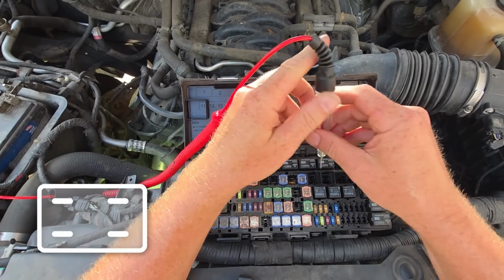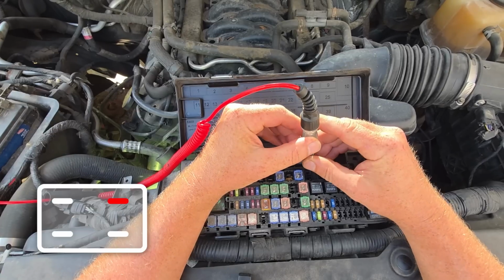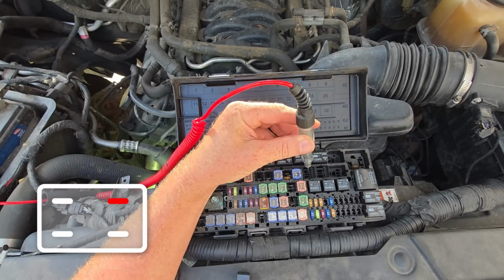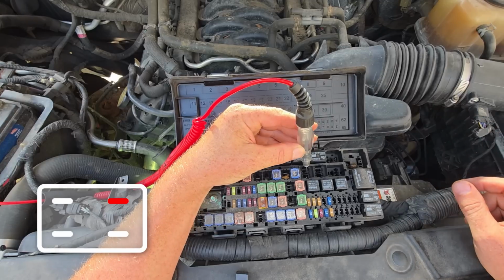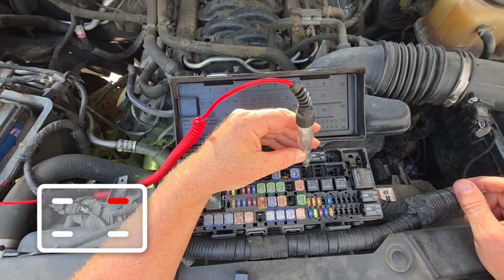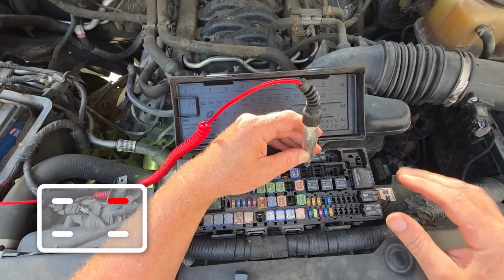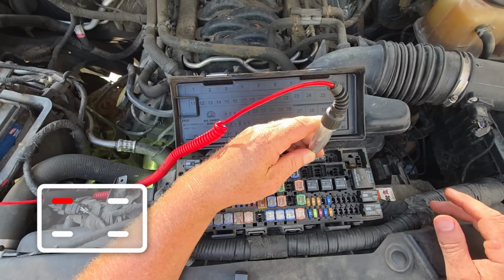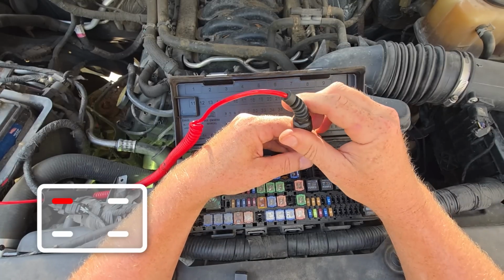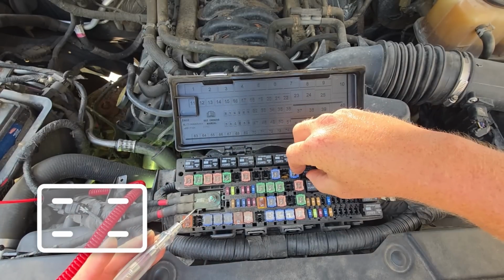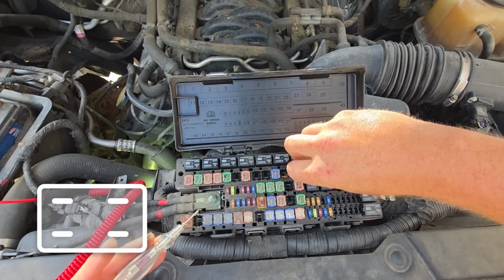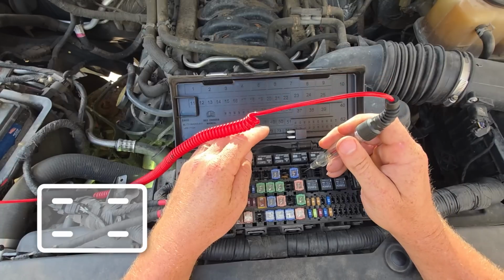And one of these two pins up top should show a ground when he starts that and turns the air on. Do it? Yeah, go ahead. We'll start with the top right. Just want to make sure I'm on the right relay. Air's already on, right? I'm not showing a ground. It has to be, because when I plug this in, it's clicking. So what am I doing wrong?